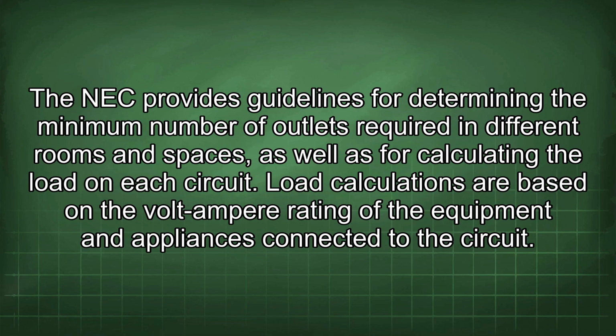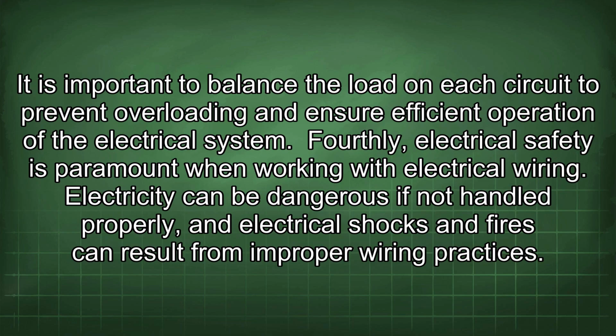The NEC provides guidelines for determining the minimum number of outlets required in different rooms and spaces, as well as for calculating the load on each circuit. Load calculations are based on the volt-ampere rating of the equipment and appliances connected to the circuit. It is important to balance the load on each circuit to prevent overloading and ensure efficient operation of the electrical system. Fourthly, electrical safety is paramount when working with electrical wiring.